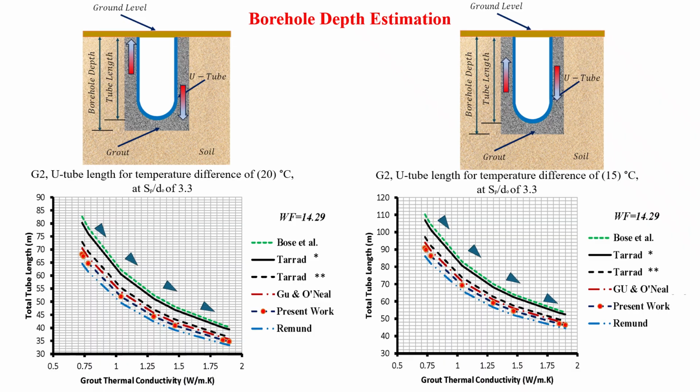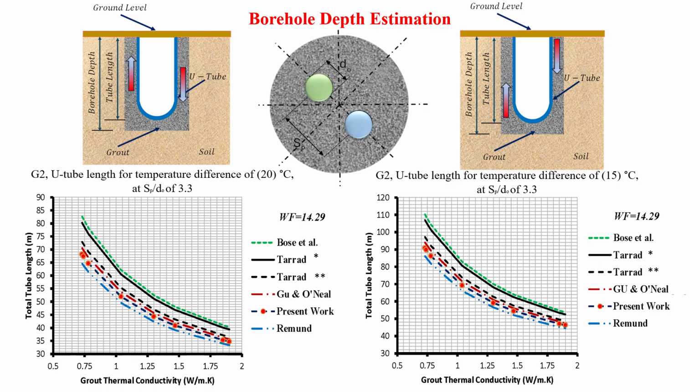Of course, these values mainly depend on the temperature difference and the total resistance, which has been calculated throughout this episode. And in that effect, we have to mention that the orientation of the single tube in the heat exchanger has no effect, in fact, because we are only dealing with one single U-tube, and this can be vertical or horizontal.